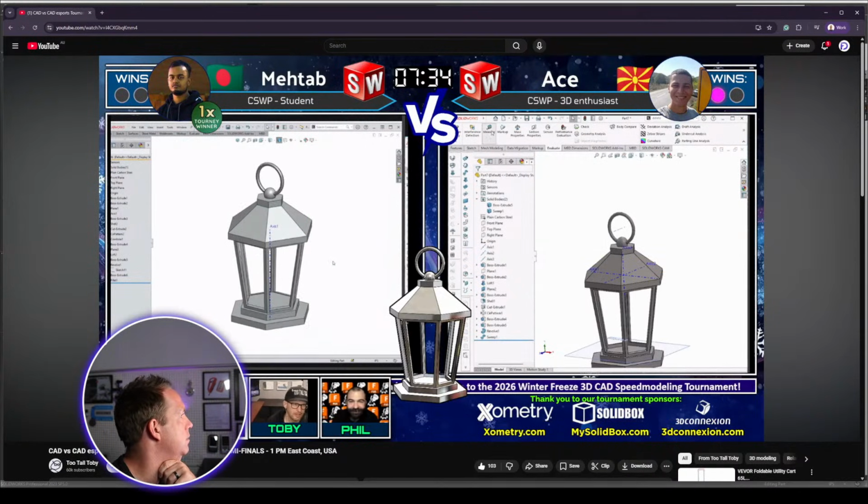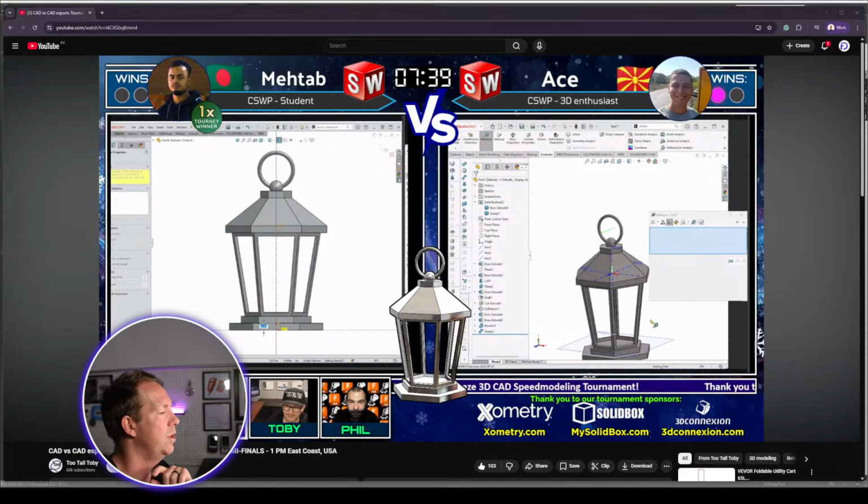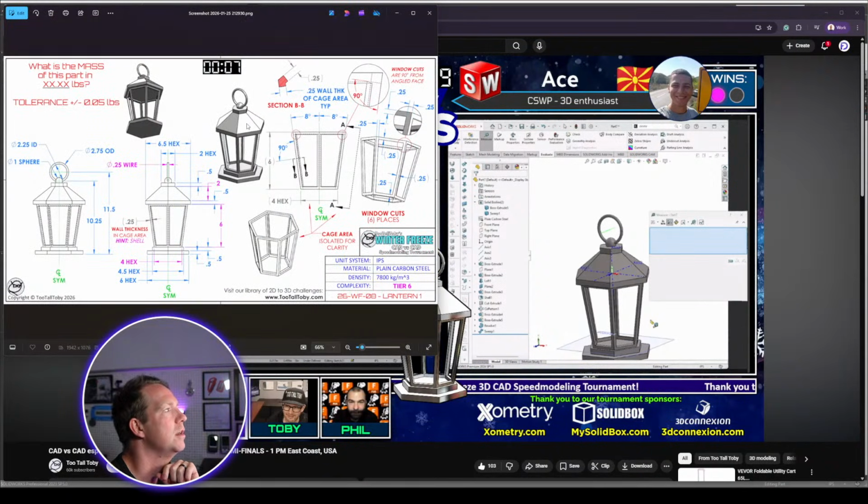Yeah, gotcha. That would have been really smart, actually. So I'd say his point here is this top section of the roof. If you just draw that hex, the 2 hex, you could extrude one up 0.5 and the other one down 2, but you don't have the angle for the one that is going down. You'd have to manually work it out, which would take extra time. Like you could do it, but it wouldn't be a very efficient move.